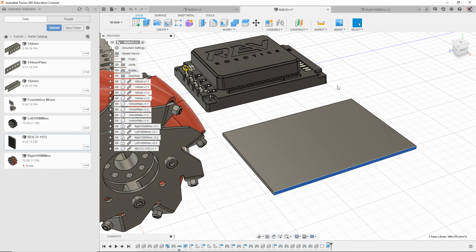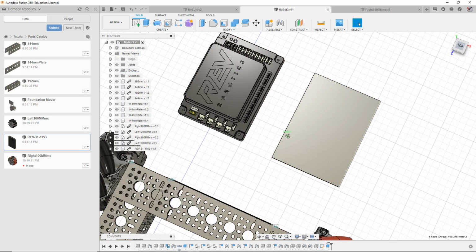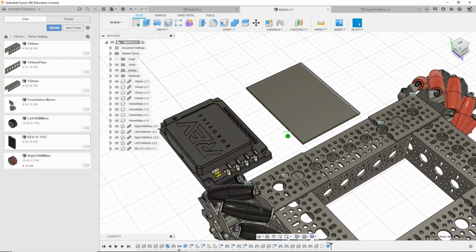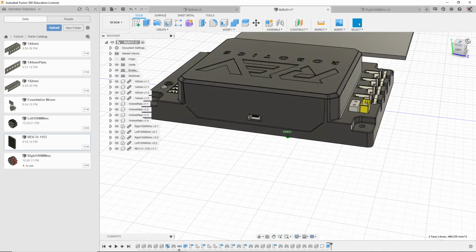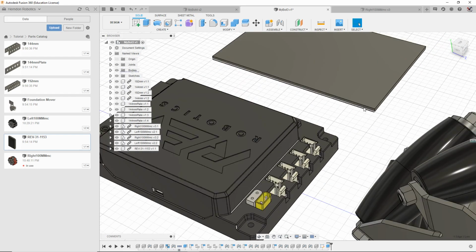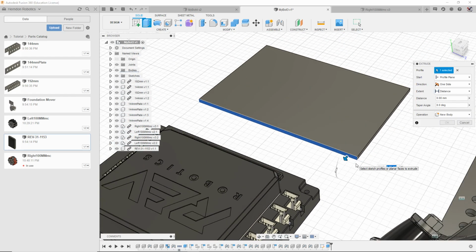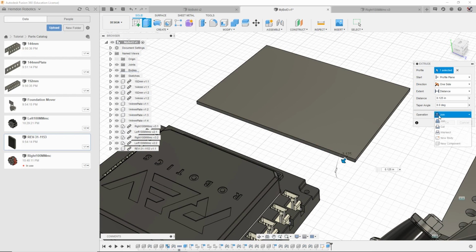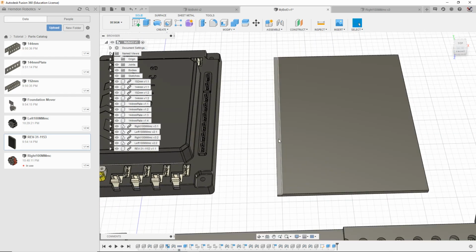Then we're gonna come here, because we need some other place. We could just put it on the back like this, but I don't want to do that. I want to show you a little bit more complicated thing. Although I am gonna do it on this side. There is a port right there. We're not gonna worry about that, because I just want to make this a quick tutorial, just show you guys, introduce like I've been saying. So click here, hit extrude, and then we're gonna make 0.125 inch again, and then we're gonna hit new body. The reason we chose new body is because we want to be able to extrude this again without making a sketch and making it really complicated.